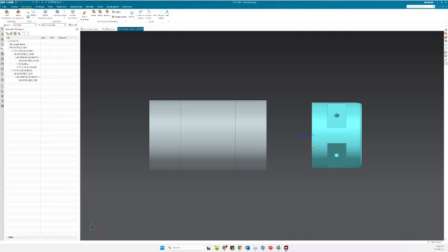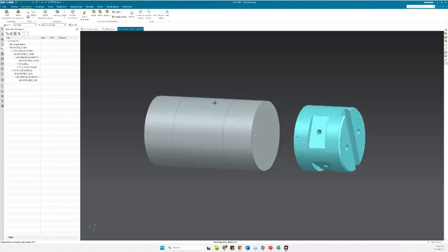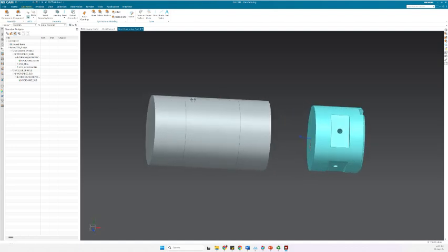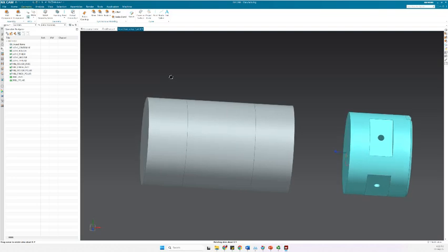When we define the transparency and then hide the part, we are able to see what these two components are. I have the feeling that there are two components now created, so we need to remove one of them. But that's not a big deal. We can do that. So to be able to visualize the part here, I'm not able to right click and just define the transparency as some software allows me.